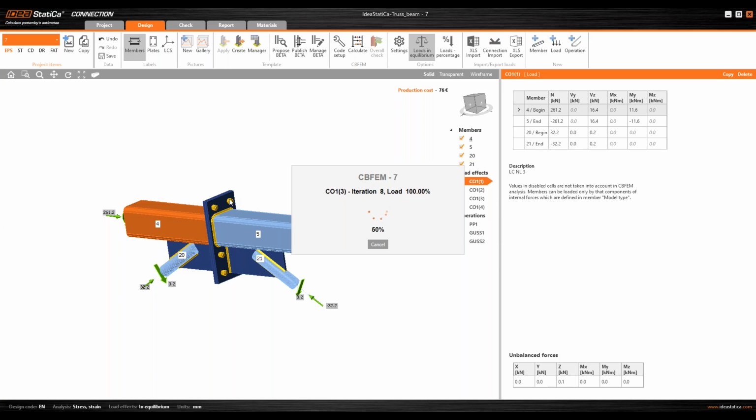And the welds will be code checked for equivalent stress. So all normal stresses and shear stresses in the parallel and the perpendicular direction are considered in the equation for code checking of the welds. You can see we have 4 combinations,